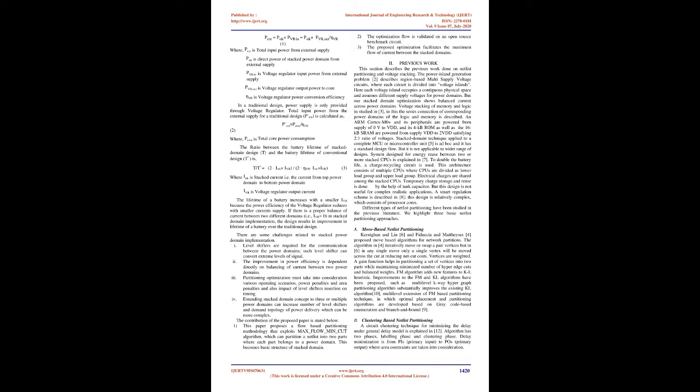Battery lifetime, T, and external power, PEXT, are inversely proportional to each other. In a stacked domain, PEXT equals PSTK plus PVR_in equals PSTK plus PVR_out / ηVR, (1). Where PEXT is total input power from external supply. PSTK is direct power of stacked power domain from external supply. PVR_in is voltage regulator input power from external supply. PVR_out is voltage regulator output power to core. ηVR is voltage regulator power conversion efficiency.